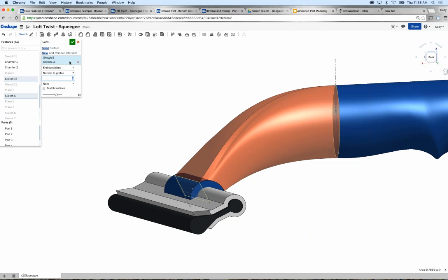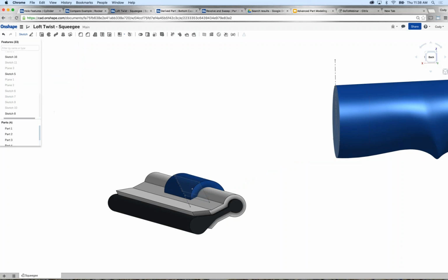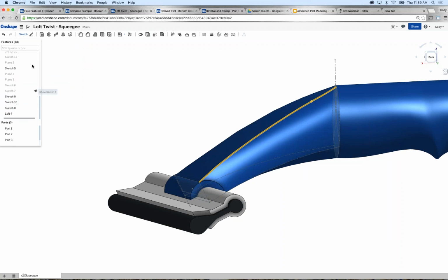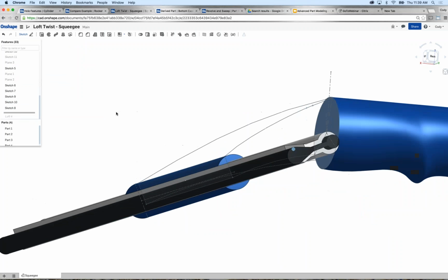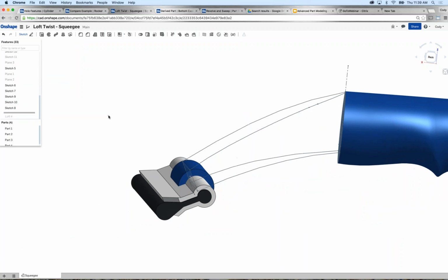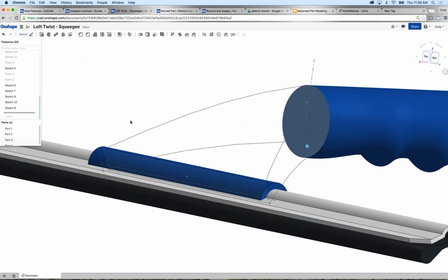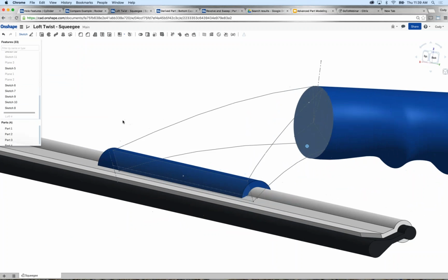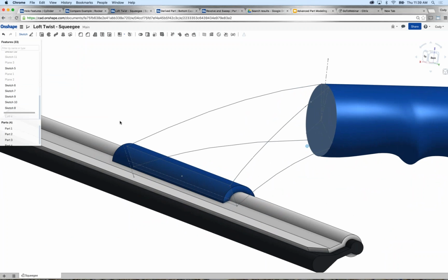However, if you want the utmost control, all the detail in the world, you can use guides. Now, guides will take you a little bit longer to set up, but they're very, very powerful. And the reason I say that is because essentially what you're doing is you're controlling the transition between shapes, not with in conditions or with splitting entities, but with actual sketch geometry. So here I've turned on my guides. You'll see there's guides going from each point in my circle to each point in my rectangle. But the important thing here is now I'm very accurately controlling the transitions, right?